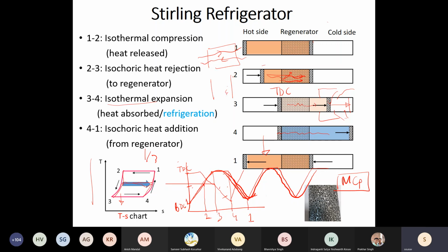So this is the second type of heat exchanger. These are storage kind of heat exchangers. They are not steady heat exchangers. So you can have a honeycomb structure or any form of porous media, and when the hot stream passes through it, the structure stores the heat and releases it when the cold stream passes. So this is how the porous media looks like. As the name suggests, it's just porous material.